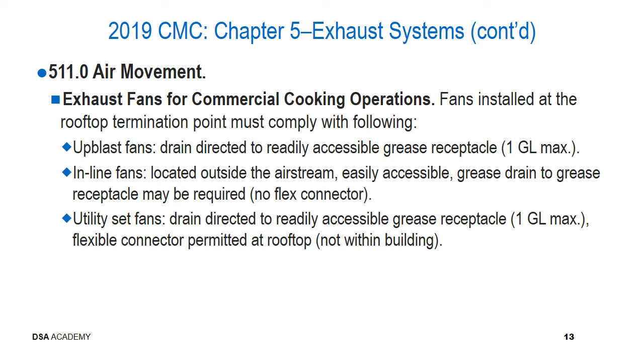So for Upblast fans, the grease is going to be drained directly to a readily accessible grease receptacle, which is 1 gallon max in size. And of course, this receptacle is going to have to be emptied by staff, maintenance personnel on a regular basis.